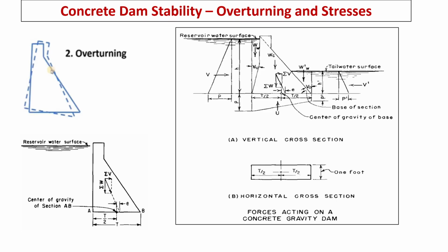We all know the middle 1/3 rule. That is, if the eccentricity falls out of the middle 1/3 region, there is a chance of tension developing. The same technique applies here also. Maximum care has to be taken to restrict the eccentricity within the middle third. In some unusual or extreme load cases, little or minor tension is allowed and its limits vary from various standards as applicable. Here eccentricity is towards the toe, that is the B side.